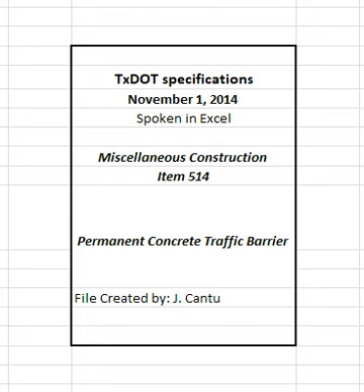3.2.1 Conventionally formed barrier. Accurately set forms for conventionally formed barrier. Secure the forms in a manner that is not detrimental to roadway pavement and will maintain barrier in a true position during concrete placement. Remove forms after the concrete has reached sufficient strength to prevent physical damage to the barrier.